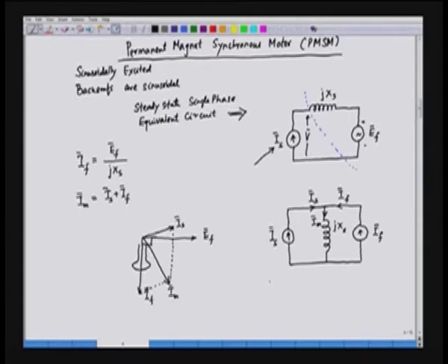What about the voltage? The voltage which is available here, this voltage V, is because of Im. So, in this case the relationship between Im and the voltage V will be 90 degree. So, what we do here is that we draw here a line which is again pi by 2 with respect to Im, and this voltage, this is voltage V in this case. So, this is the voltage V here,